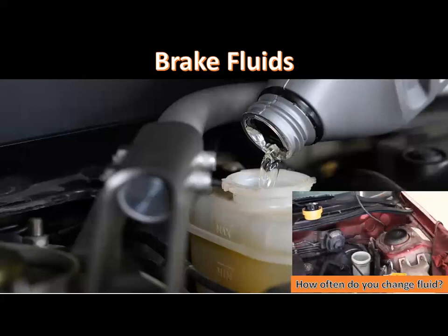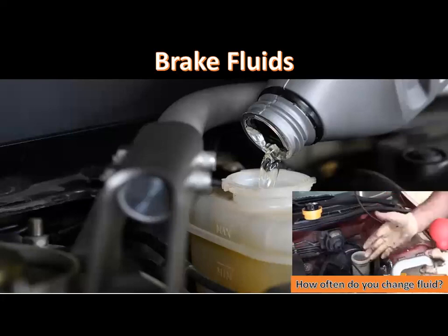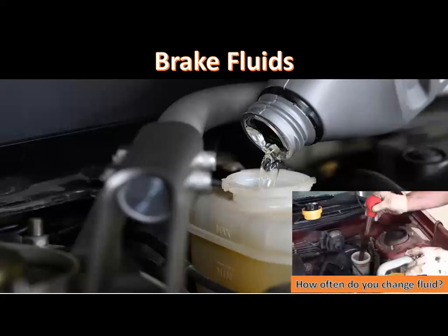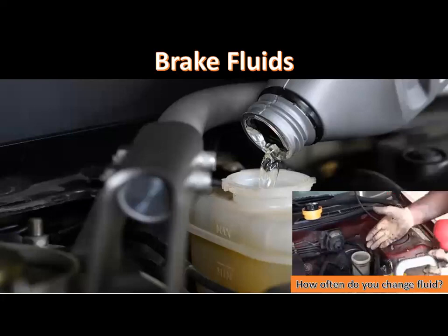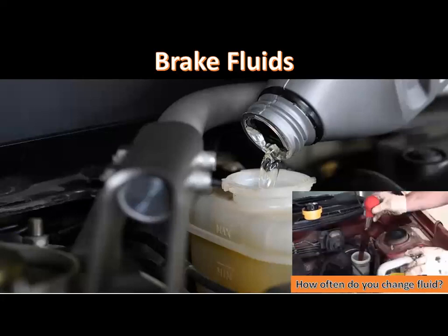Brake fluid must operate at temperatures from negative 104 degrees Fahrenheit or negative 75 degrees centigrade to 500 degrees Fahrenheit or 260 degrees centigrade. Brake fluid must be compatible with rubber in master cylinder cups, wheel cylinder cups, caliper seals, and brake hoses. Lubricating ability. Brake fluid must have a satisfactory lubricating ability to provide smooth operation of brake components.